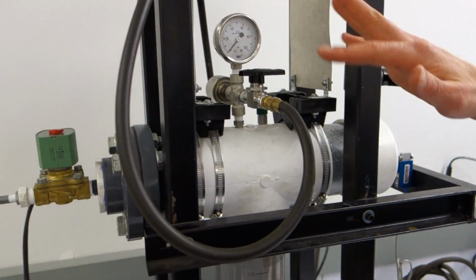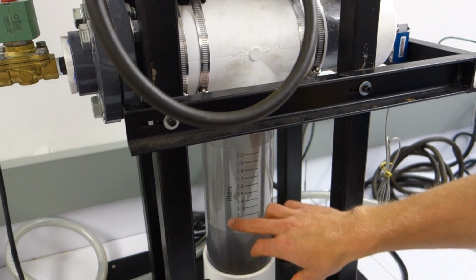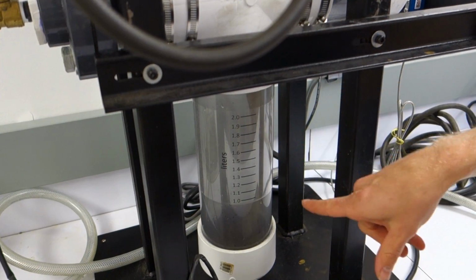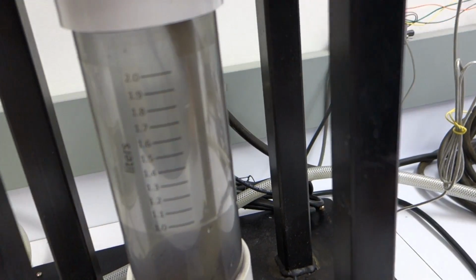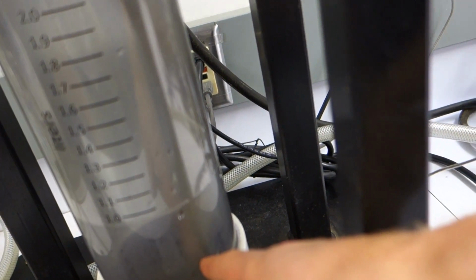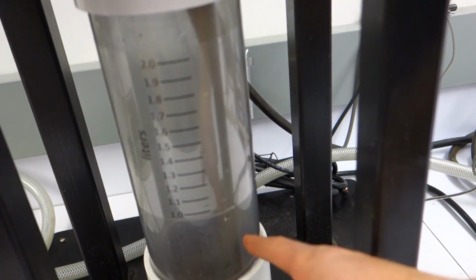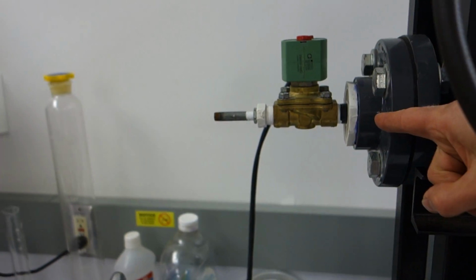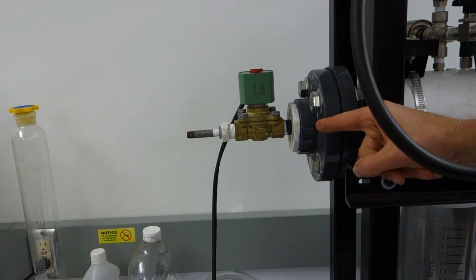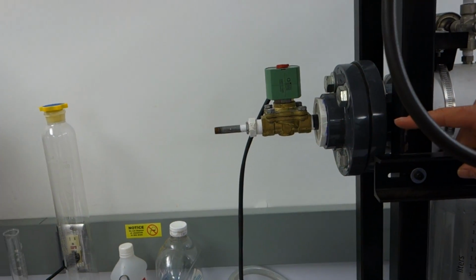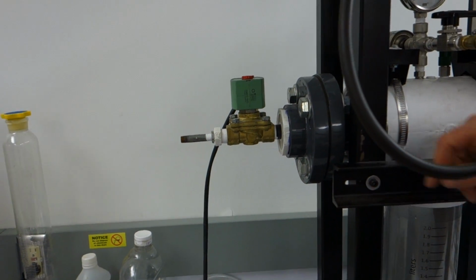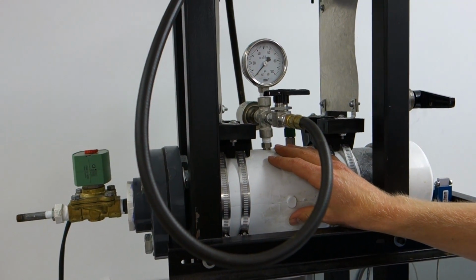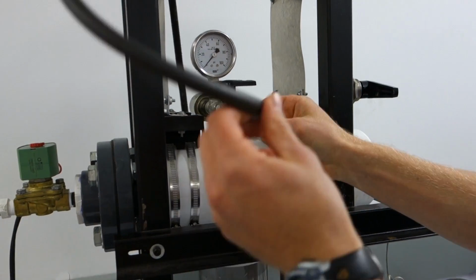We see there's a tank here for water. It's measured in liters. We're going to be filling this tank up to 2 liters of water. And if you look inside the tube, it's kind of hard to see, but there's a tube that dips down into the bottom of the tank here. That's a dip tube, and it runs the length of the device up and around to the nozzle, which is attached to the valve. And so the water is going to get ejected out of the nozzle via some force that's pushing on the free surface of the water, and that will be the pressurized air.